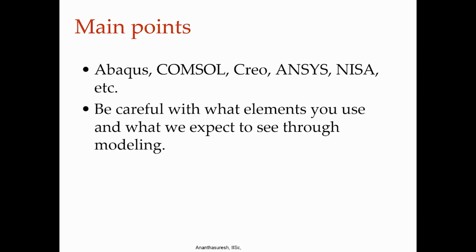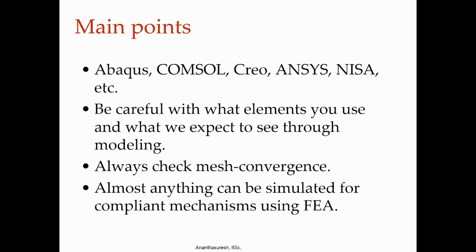And we have to be very careful with the element type as well as the mesh convergence. You have to use a sufficient number of elements to make sure that your answers are close to reality. And let us note that almost anything can be simulated using finite element analysis in the context of compliant mechanisms.